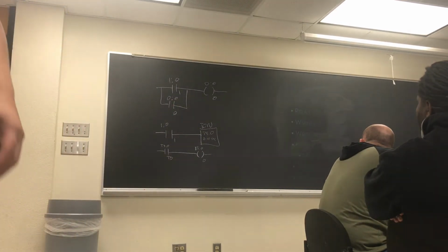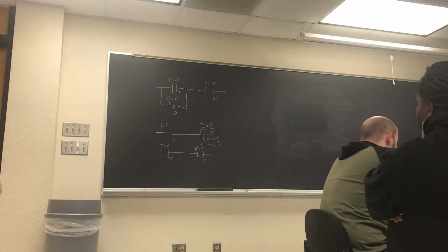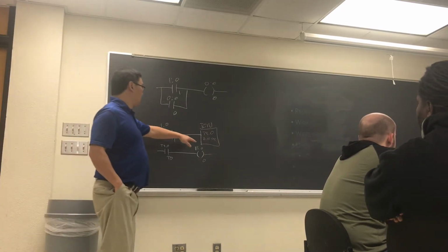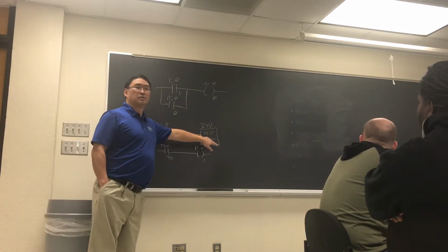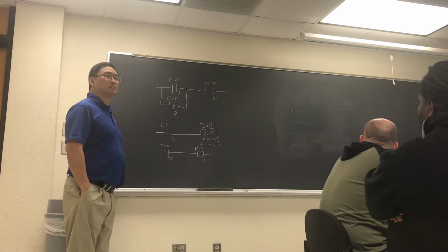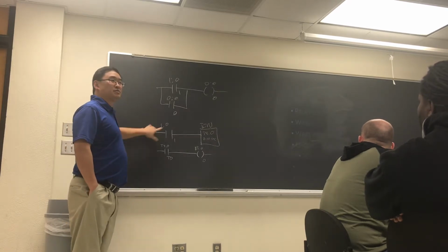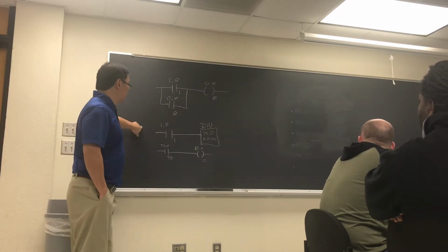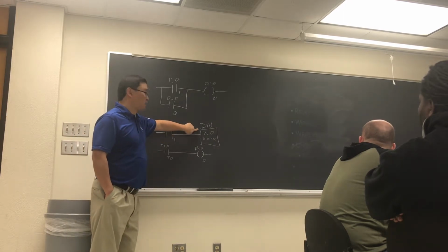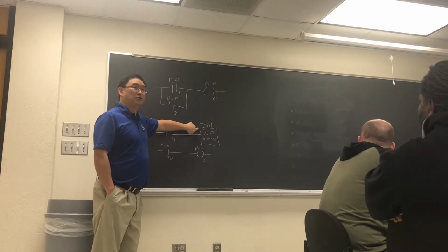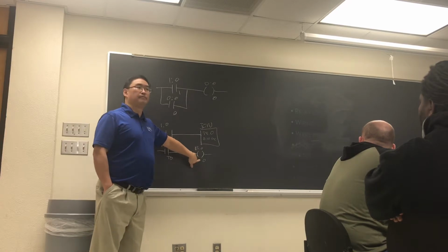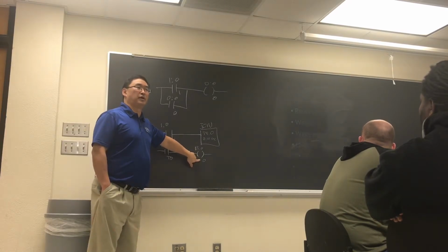What kind of logic is that? It's timing, it's like 10 milliseconds timing. Yep, it's 100 milliseconds, you're right. That's fine. Remember the debounce, the conveyor? So this has to be turned on for 0.1 seconds before I acknowledge that the part's really there, right?